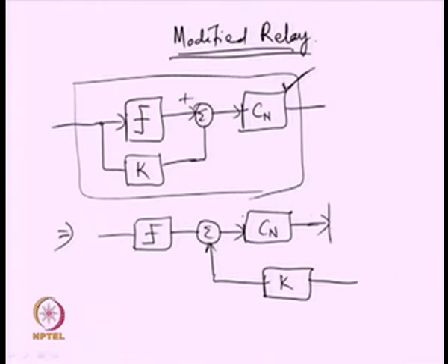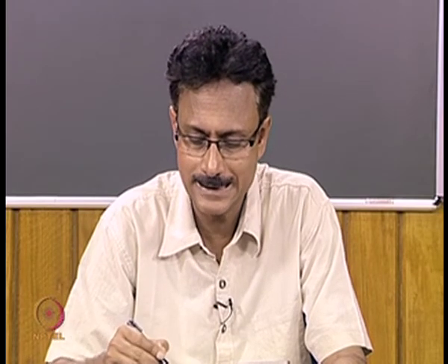So, when I have got my Q1 here, okay, because the loop interactions have gone, with the proper choice of Cn, it is possible to eliminate the loop interactions, and the TITO system can equivalently be represented by a transfer matrix which has got only diagonal elements Q1 and Q2.